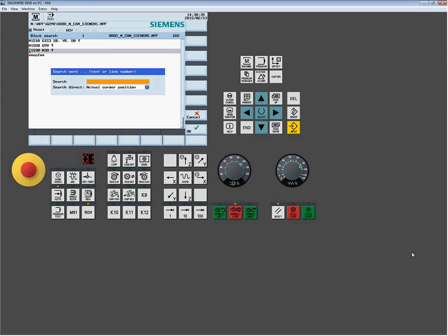Another question came in just before. How many jog moves can I do before I restart? As many as you want. There's no limitation, at least that I know of, as far as the number of jog positions. But remember, the system is going to vector to the starting point. So make sure you leave it in a safe spot where it's going to go the shortest path. It's going to do potentially up to a 3-axis move to get there. So it's pretty common to move away and then jog back close before you restart the system, so that the vector isn't that great.